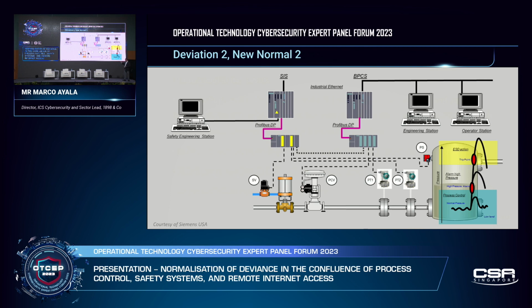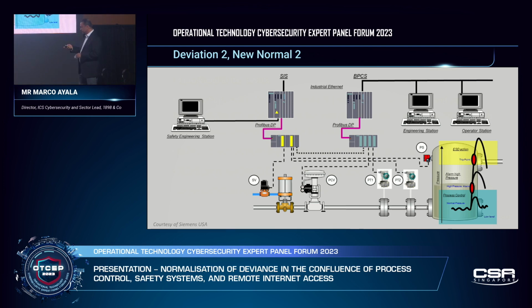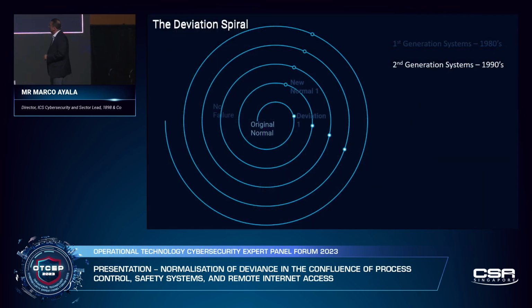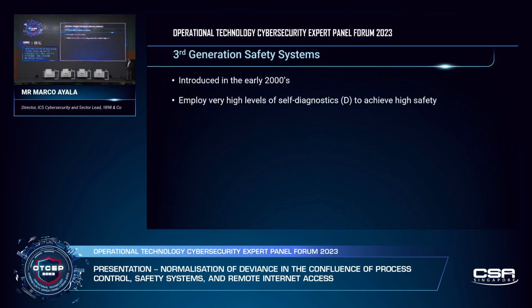And I don't know if you can see the laser, but we had hardwired I/O from the safety system back into the basic process controller, the DCS. Or we had a serial network going peer-to-peer, non-switched, non-networked. And so this was the typical norm. When we went to this, we started to go to a second deviation, which was allowable, using Windows OS very early in its infancy.